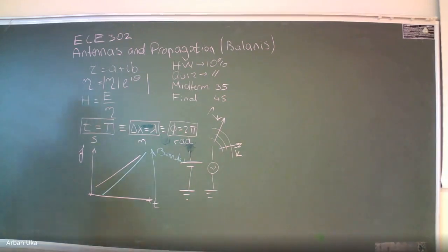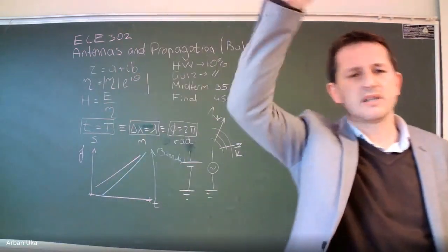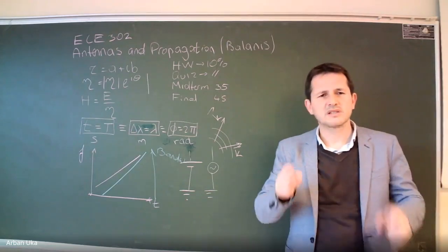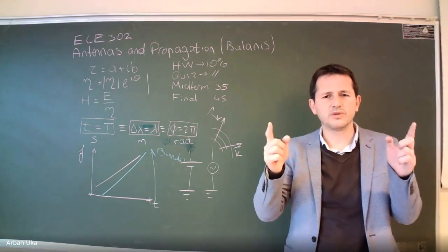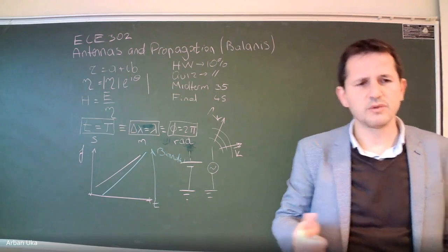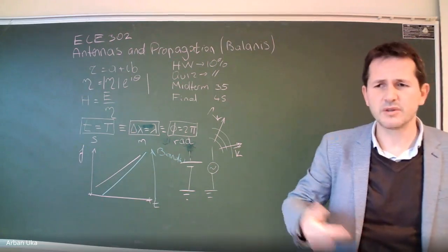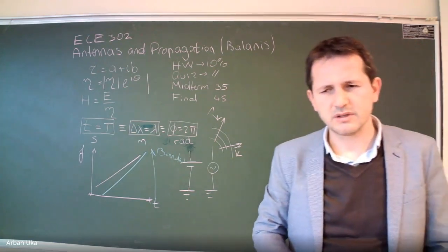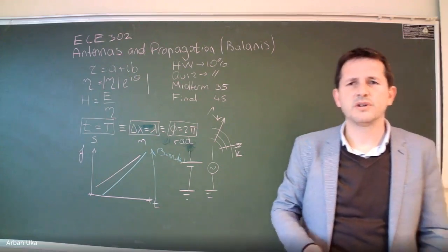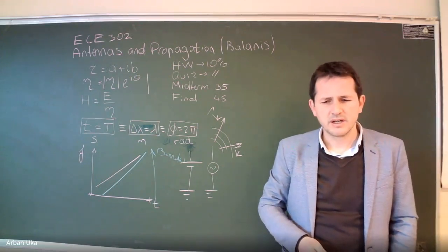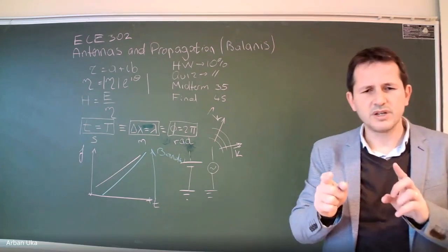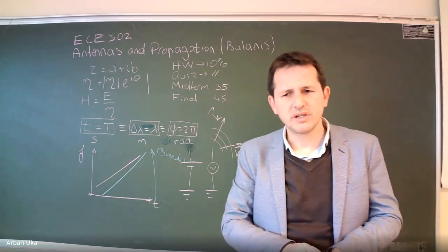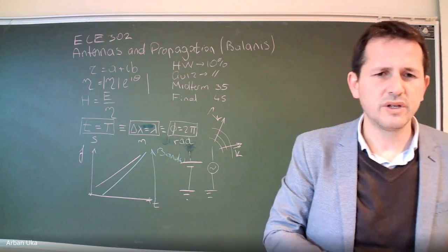So if you see anything which oscillates randomly because you have a wire extending out there, this is because you're picking up specific frequencies where the size of this wire component that is picking up the signals is comparable to the wavelength of the signal that is coming through. In the courses that you have taken in the past, you might have heard lecturers say several times that whenever there is communication between one component and another, the matching in frequency is essential, but also the matching in length scale is essential.